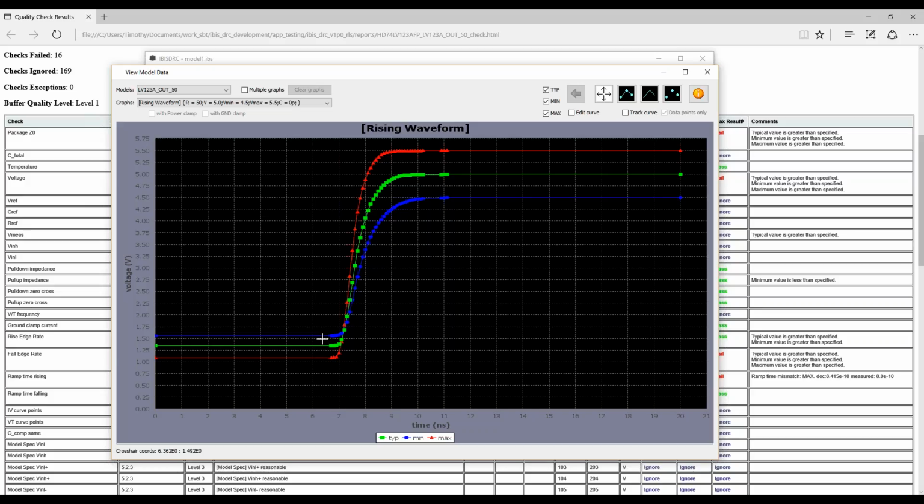So probably what happened is whoever developed this model was trying to force this time window to be 20 nanoseconds, right? Because essentially this time window, if you remember, defines the max frequency of this IBIS model switching. So they're probably trying to make this switch at 10 nanoseconds, or like a 100 megahertz output. The data sheet says that the TCO there should be 5 nanoseconds, so they're trying to force it. And in reality, you don't want to do this.